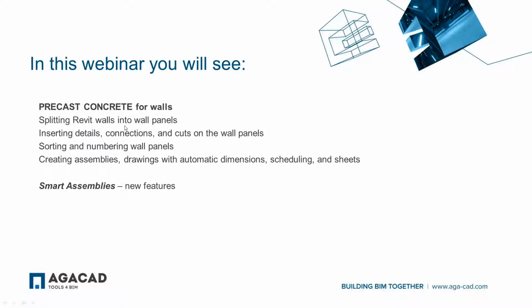In this webinar, we'll see how to work with walls, how to split them using our tools in Revit, how to insert details, connections, and cuts to model the panels, then automatically sort them and create drawings, which have automatic dimensions and different options. We will also mention some new features for existing users, so you know what new functionalities the next update will bring.